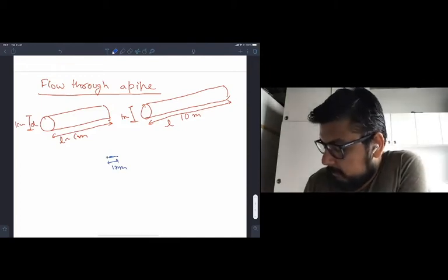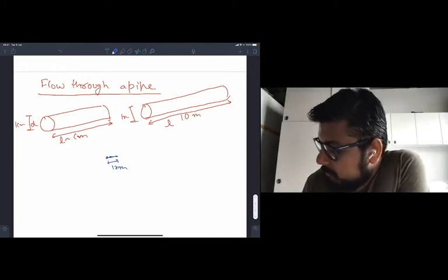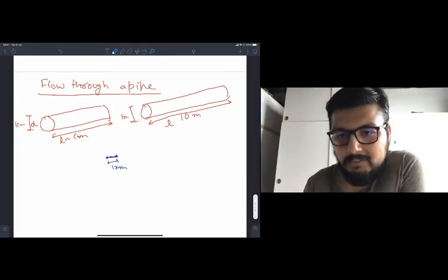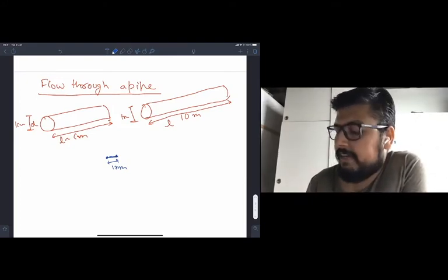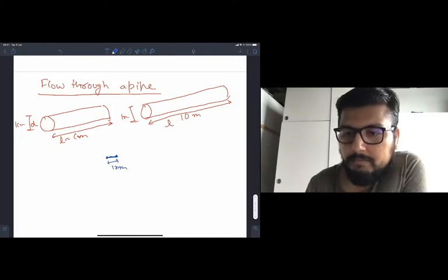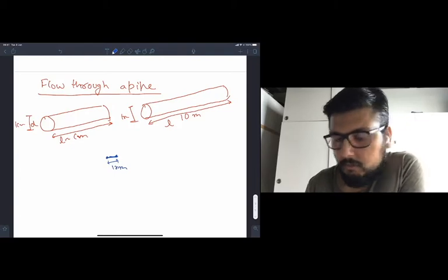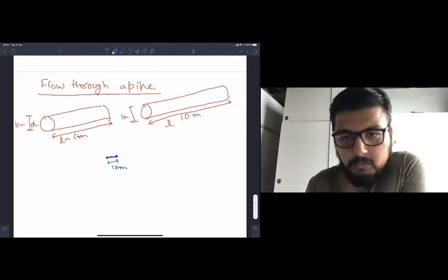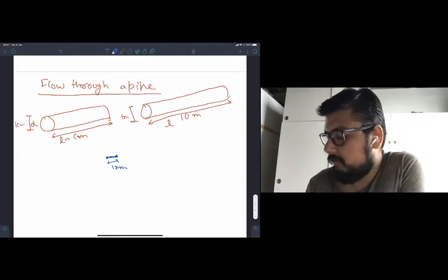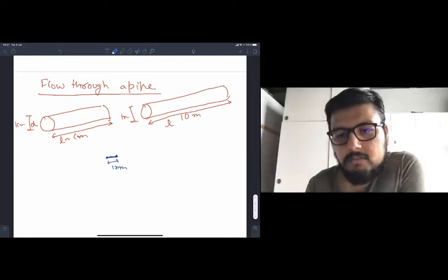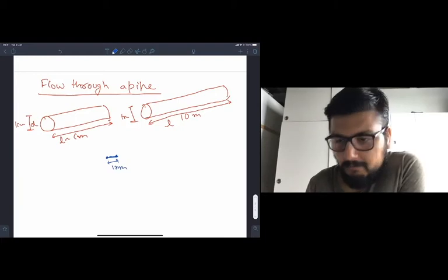So you have to take my word that this is 1 nanometer. So if we have a pipe which is 1 nanometer in length, then of course the laws of physics are going to change, because we will need to take into account some new forces that we don't have, let's say, in the Navier-Stokes equation. Also, Navier-Stokes equation is a continuum model, right? So we can only talk about cases where the continuum hypothesis is still valid.